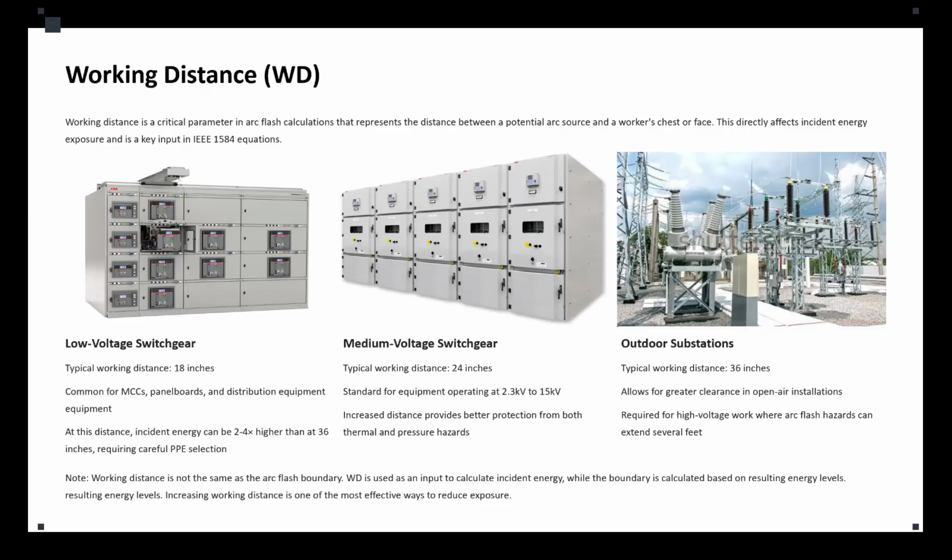Why does working distance matter? Because it directly influences the calculated incident energy at the worker's location. We already said that when you talk about incident energy, there is always a distance that helps us calculate it. It influences the required arc rating of the PPE, and it influences the computed arc flash boundary.